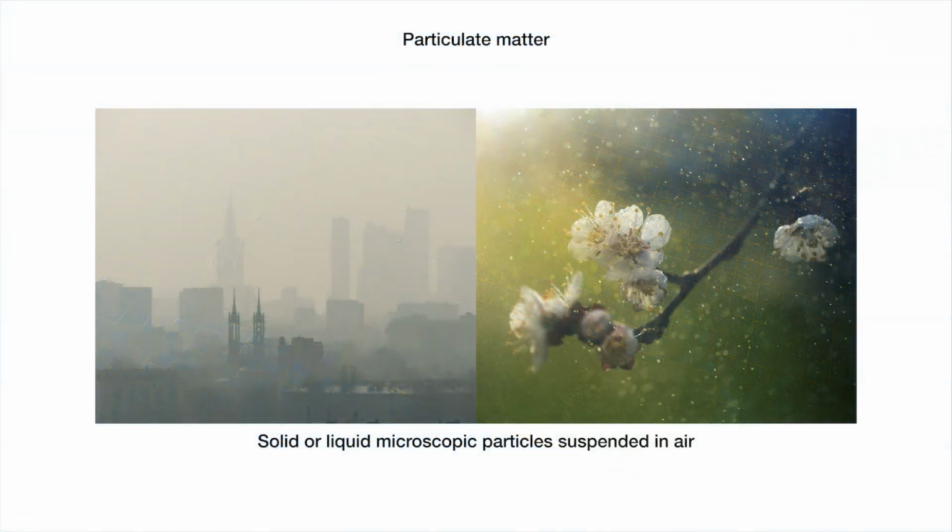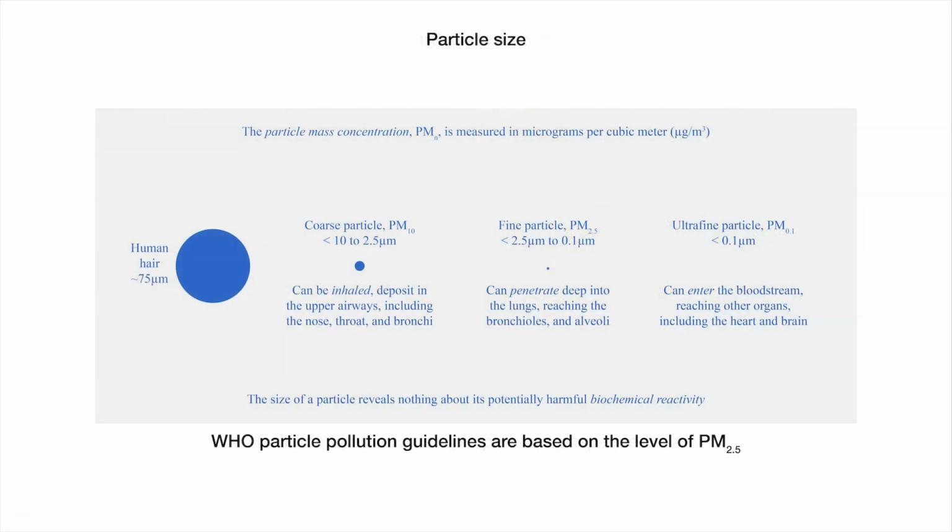You'll measure particulate matter, which means microscopic solid or liquid particles suspended in air. The source of airborne particles could be combustion processes in industry or road traffic, but also cooking or pollen. As far as human health is concerned, you're looking at particles below 10 micrometers.